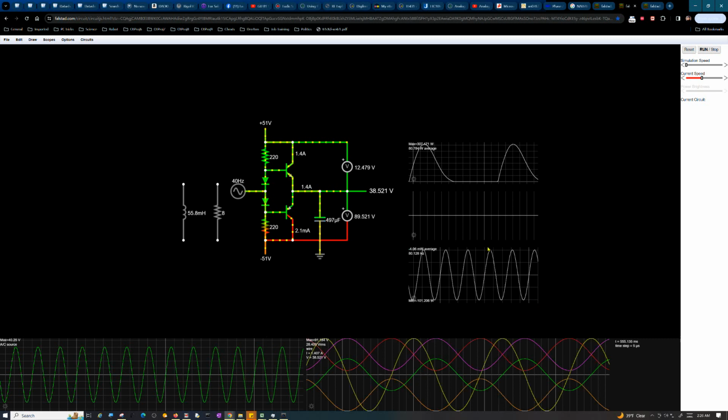But yeah, you can show what the apparent power dissipation is, and this is all apparent power, because you got a certain current and a certain voltage across this thing. You'd think, hey, that's consuming a bunch of power. Well, no, it's not actually. It's just apparently consuming power, but in fact, it throws it back into the system, and that's what happens here. The device itself isn't consuming any power, whereas the transistor here that's driving it is. In fact, you can see that's peaking at like 307 watts here, in this simulation, at peak power.